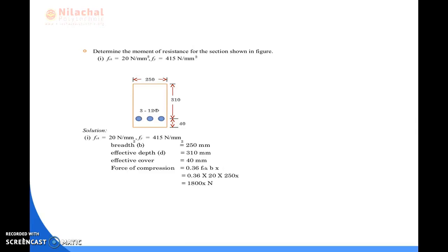In an under-reinforced section, the steel reaches its permissible value earlier as compared to concrete. So in case of an under-reinforced section, we can design a section. The failure chances are less, and it provides a symptom before failure. But in an over-reinforced section, the compression force, it means concrete, reaches its permissible value earlier as compared to steel. So we cannot assume the section.